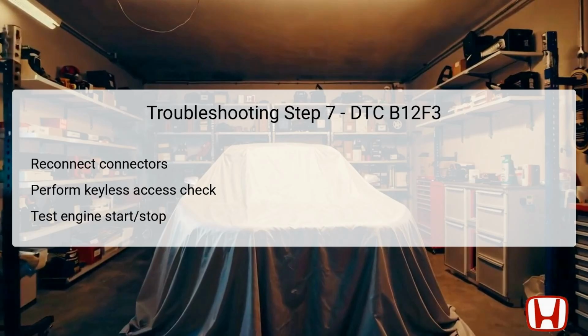Start by disconnecting the vehicle's 12-volt battery terminal and allowing a wait of at least 10 seconds for the system to reset. After waiting, reconnect the battery terminal. Now, transition the vehicle to the on mode before moving it back to the off-lock position.